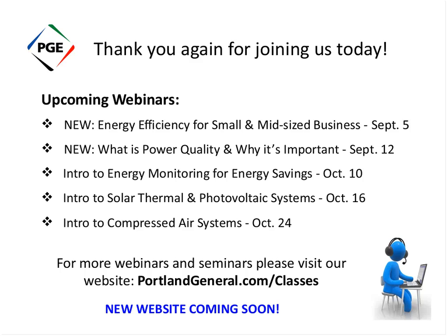But since T8s are much smaller in diameter, the surface area is probably only half as much, so they only need half as much of those phosphors. So the larger T12, higher color rendering lamp is going to be more expensive because it needs more of those phosphors in order to meet the 87 CRI requirement.